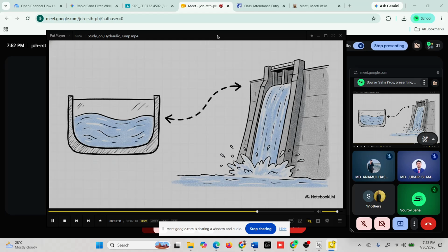Because our Froude number was sitting right between 1 and 1.7, the resulting water surface just showed some slight undulations, rather than a massive plunging roller. It's literally the gentlest form of a hydraulic jump. It's perfect for a safe laboratory demonstration, but make no mistake, it's operating on the exact same physical principles as the massive roaring jumps at the base of the Hoover Dam.